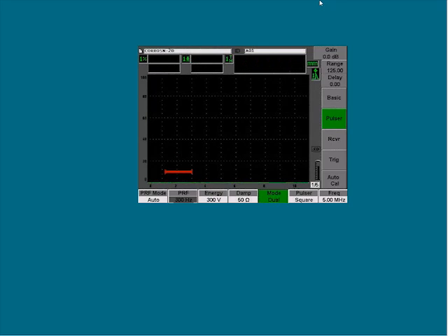This actually is a very common support call that we get here at Olympus from our flaw detector users: people forgetting to switch the mode to dual when they plug in a dual probe. We also will look at our square wave pulsar setting, and we'd like to optimize the width of the pulse for our 5 megahertz probe, which is actually the default setting for this unit. So that's already optimized.